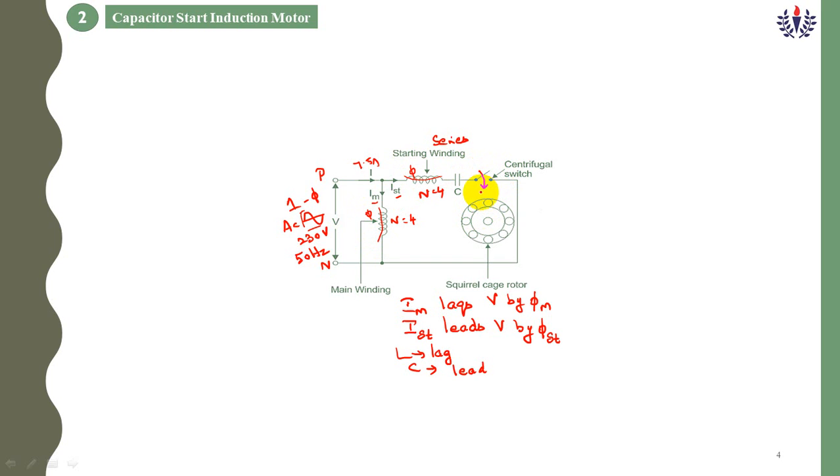Once you close the switch, the current in the starting winding will energize and charge the capacitor, then the machine starts running. Once the capacitor charges, the machine immediately starts running slowly. Now you have to vary this supply from 0 to 230. Once you set 0 to 230, within a second we have to release the switch.